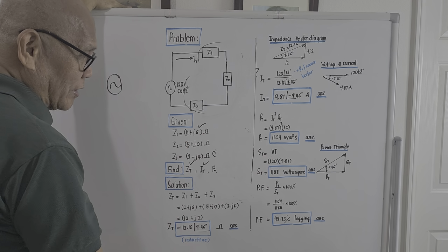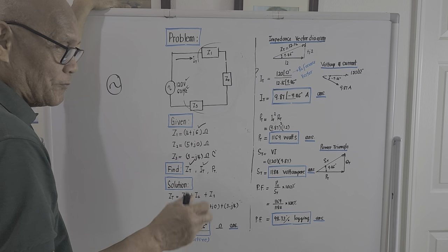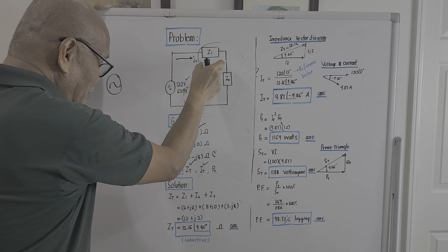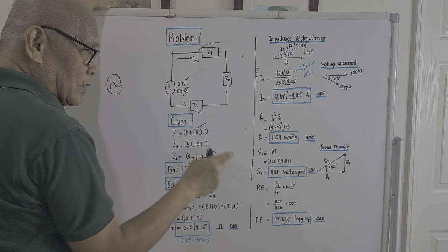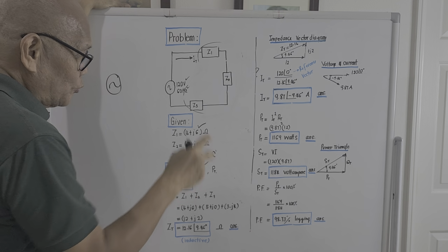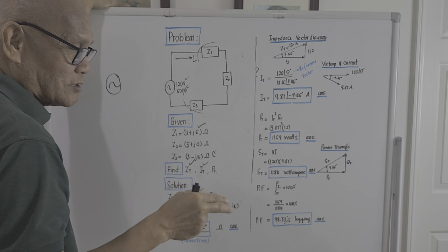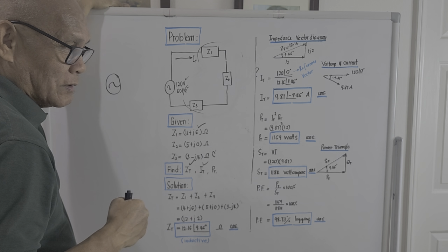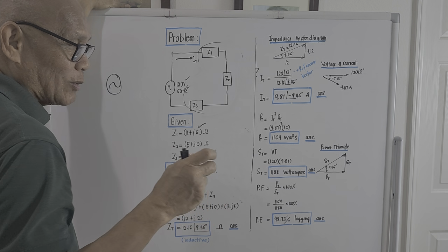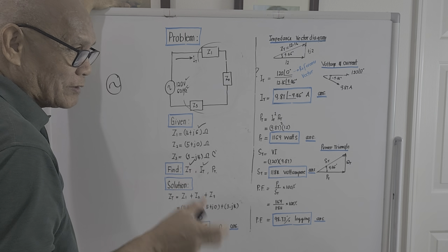For a series circuit, whether alternating current or DC circuit, the total impedance will just be simply the summation of Z1, Z2, and Z3. But under AC circuit, if we see summation, it should be a vectorial addition. It's not just simply the algebraic addition. Okay? So if we are adding Z1, Z2, and Z3, we will apply our knowledge on how to add a